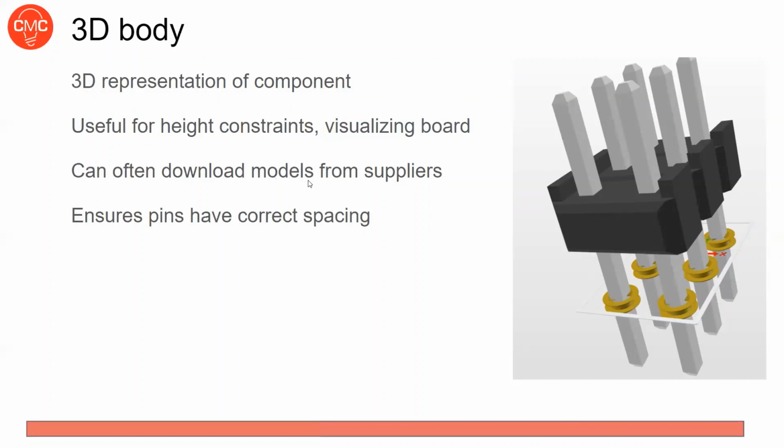Yeah, these models, like I mentioned, are often available from suppliers directly, so you can just download a CAD model and import it directly. And again, I'll show you how to do that. It's really useful to import these models also because let's say you messed up one of the spacings or did math wrong and your pins were spaced incorrectly. Importing this model and showing that it fits into those holes shows you, okay, I did it correctly. This part is actually going to fit, and you're not getting to the stage of putting your board together and, oh shoot, I put these pins in the wrong spacing. So very useful.